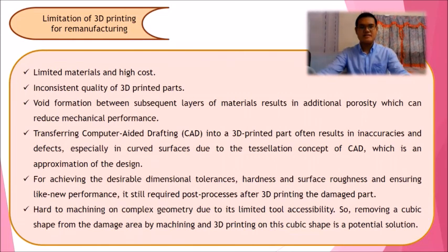Other than that, transferring computer-aided drafting (CAD) into a 3D printed part often results in inaccuracies and defects, especially in curved surfaces, due to the tessellation concept of CAD, which is an approximation of the design. Therefore, for achieving the desirable dimensional tolerance, hardness, and surface roughness, and ensuring like-new performance, it requires post-processing after 3D printing the damaged part.